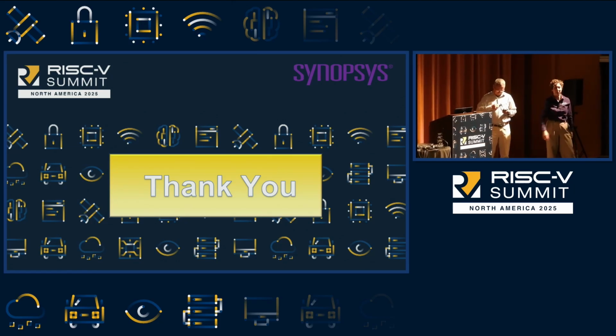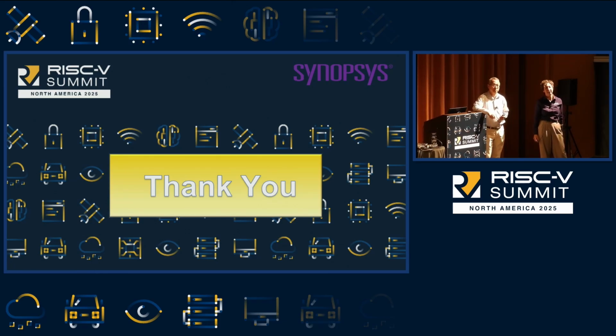Hey, this is Darshak from Tenstorrent. I think there were two main themes here: longer running test cases and the self-checking part. I have a question on each of them. You talked about running a reference model for self-checking purposes. Is the reference model run while generating the test case, or on the test bench side while running the test on the Zebu test bench? The second question is on the long-running part. Are the test cases statically generated, which means you have to generate longer test cases and they will have a bigger memory footprint, or do they actually generate longer sequences at runtime?